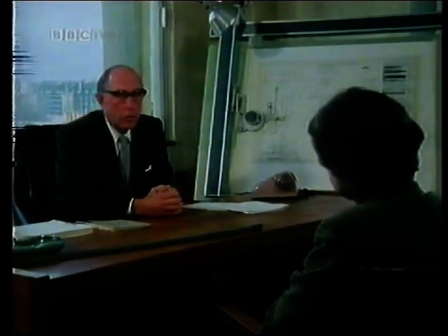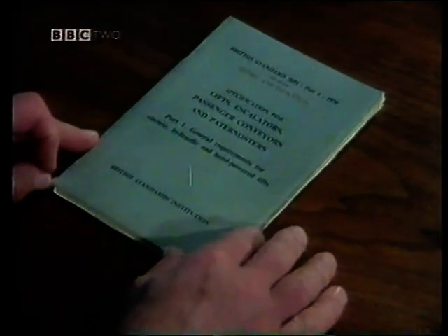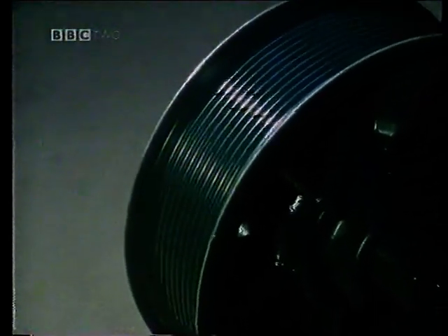Now, these safety devices are spelled out in considerable detail in British Standard 2655, General Requirements for Electric Lifts. This specification requires a minimum ratio between sheave diameter and rope diameter of 40:1. In the case of this machine, the sheave diameter was 910 millimeters, and we decided to use a rope of 16 millimeter diameter. And thus you will see we achieved a sheave to rope diameter ratio of about 52:1, well in excess of the 40:1 required in this specification.